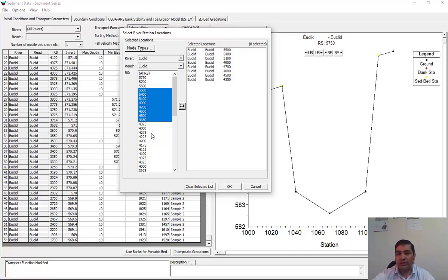If you have cross sections that are in stable conditions, you can select these cross sections, and the model won't erode or deposit them when flow goes through these reaches. Pass-through nodes can stabilize an unsteady sediment model, focusing bed change on the region of interest and running the rest of the model as flow only.